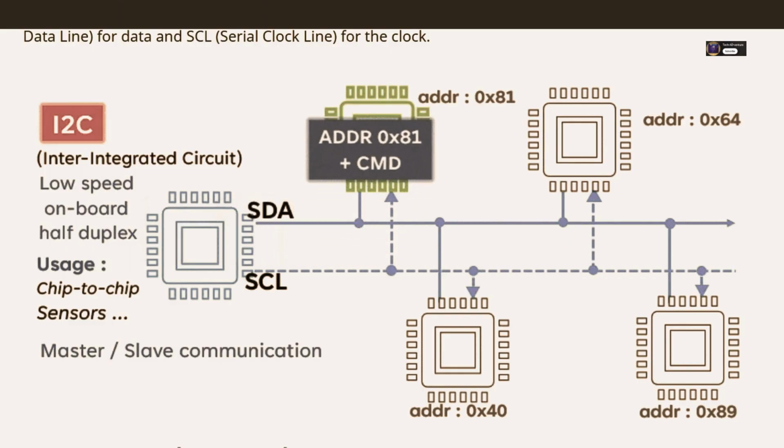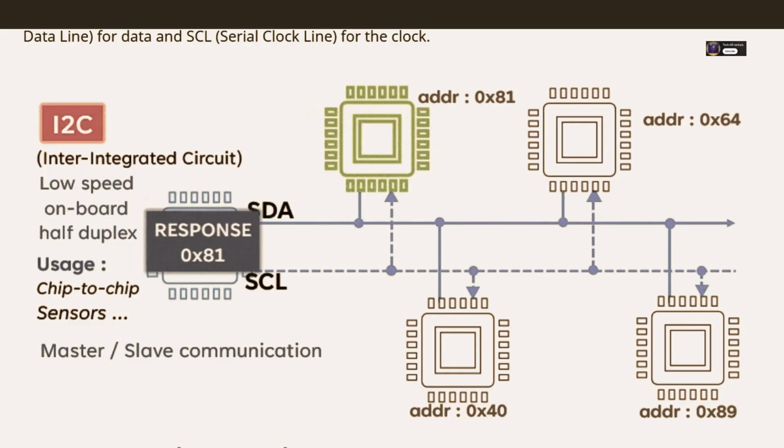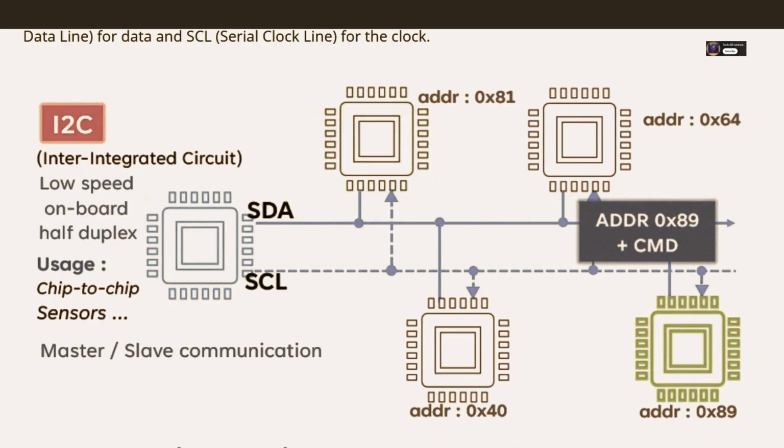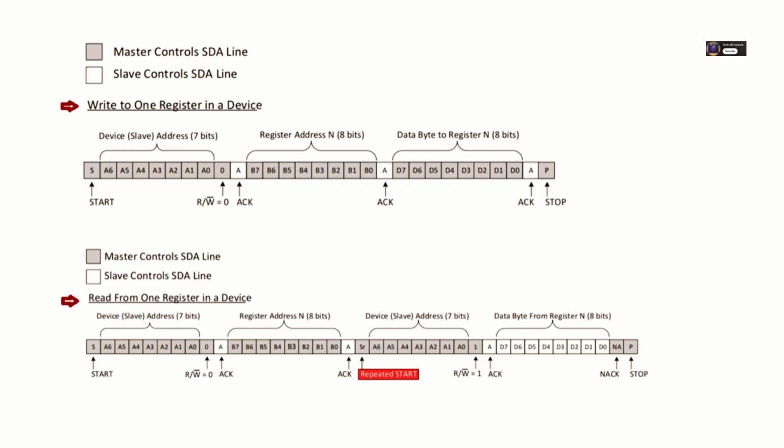And then actually sending or receiving data in code. The code then follows the protocol sequences we discussed. Generate start. Send address plus R/W. Check for ACK. Send a register address if needed. Check for ACK. Send or receive data bytes, checking ACK and NACK after each one. Use repeated start for reads where necessary. Send stop. It involves carefully managing the peripheral status flags, like byte transfer complete or ACK received, and potentially handling timeouts if a slave doesn't respond. Synchronization relies heavily on reacting correctly to those ACK and NACK signals, and respecting any timing delays specified in the slave device's data sheet.